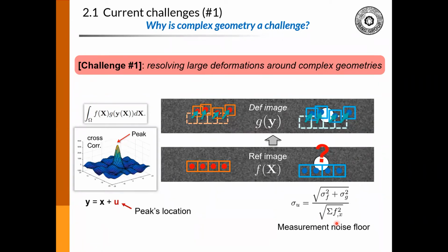Yeah, that's a good question. For the tracking, there are two tracking modes. It's based on the Lagrangian or Eulerian. The Lagrangian one is when you already know there's some pre-existing crack there, so you can just generate one mask file, using the reference image. And for the case you mentioned, if you have some new crack there, you need to make the mask file for each frame. We use the Eulerian tracking mode, so we can handle this problem.